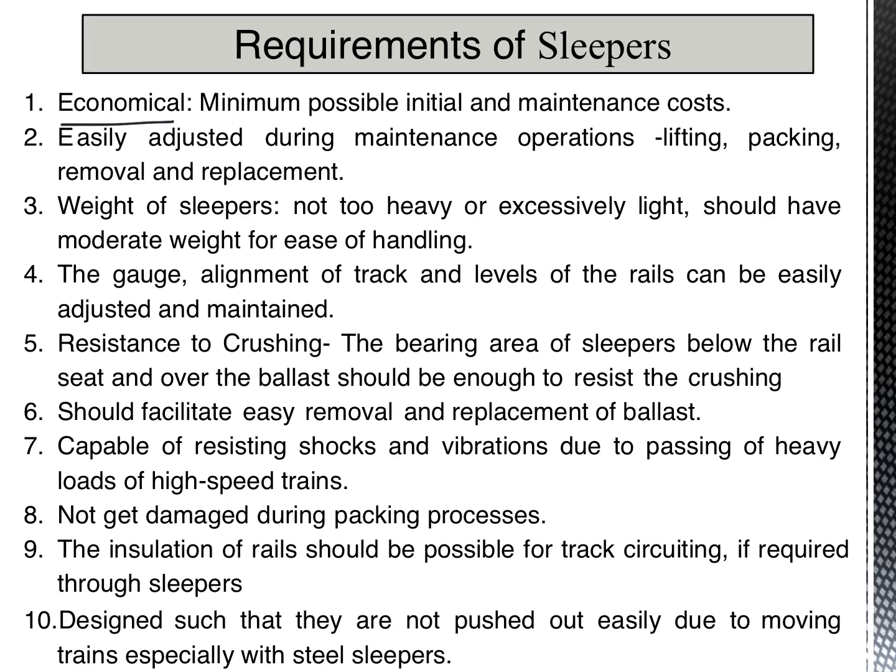The third requirement is that the weight of the sleeper should not be too heavy, nor excessively light. It should have a moderate weight for easy handling. If the sleepers are very heavy, the handling will be difficult. If it is very light, it may not have sufficient strength for load carrying. The design of the sleeper should be such that the gauge, alignment of the track and the levels of the track can be easily adjusted and maintained.